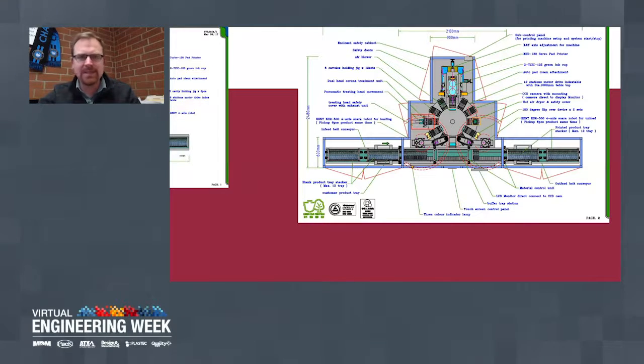Again, all these elements getting used. Here we had too many variants to actually program a camera, but we had a live feed camera so that an operator standing in front could at least look and see what was happening, make sure the prints looked okay. And then we had a little heat kicking on the parts to make sure the ink was tacked. Robot took the part, then we flipped the parts back over to the non-print side down. Robot put them back in the trays, and then they stack back up. So while they're stacking up at this position, the operator is able to take this stack out. A lot of the basic fundamentals of what we've talked about are all seen in here.